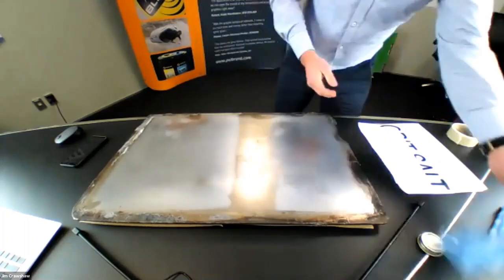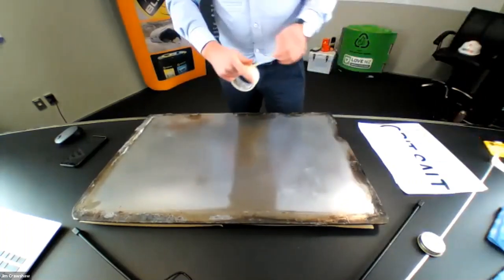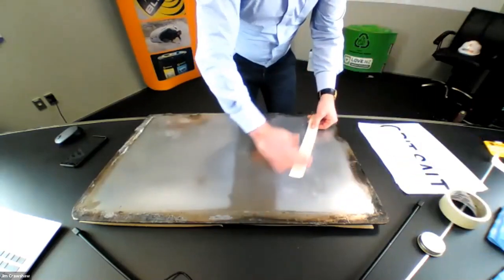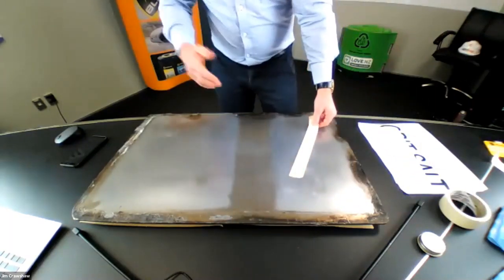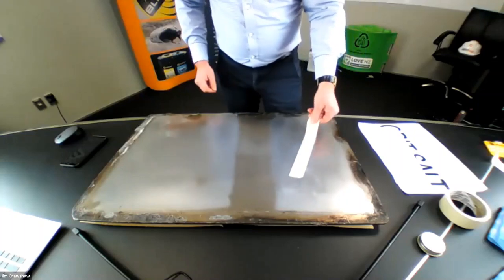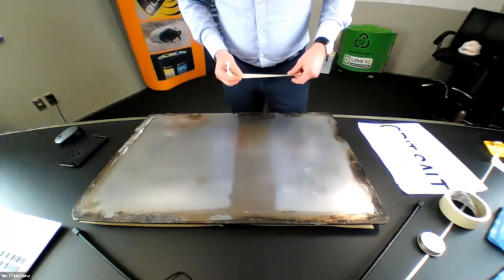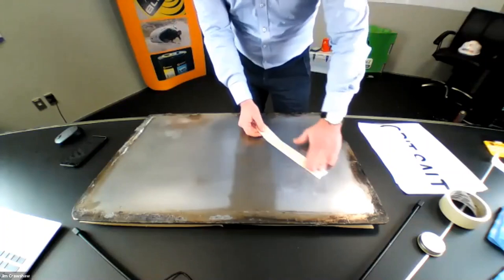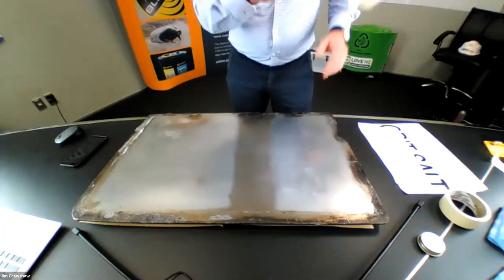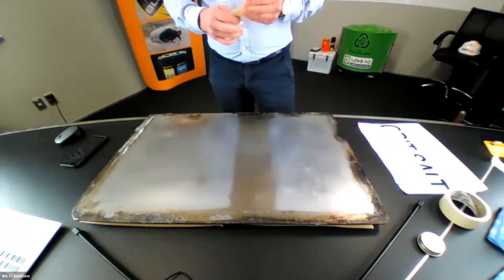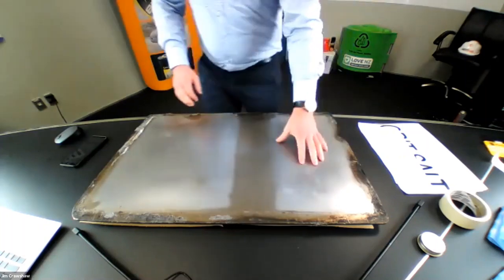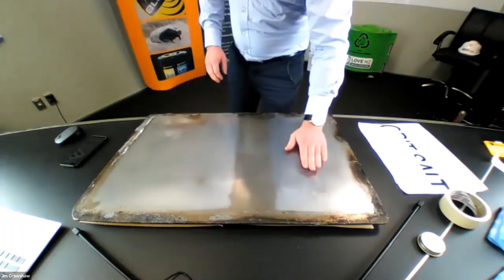So I'm going to give that a quick tape test. If I'm still not getting good results, I'll be redoing this. Sticking it down, and just listen carefully. I'll try and be really quiet. So that's the kind of noise I want you to hear. I hope that came across okay. We're sticking it onto the mold nice and firmly, rubbing it, and you can hear that distinct sucking noise when you're pulling it off. That's what you want to be listening for, and that's how you want to be preparing the mold.